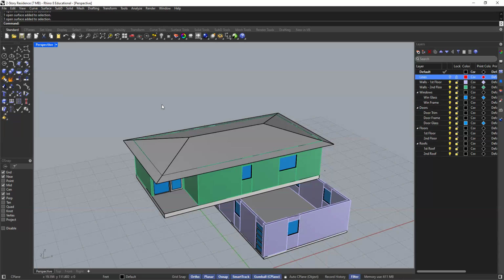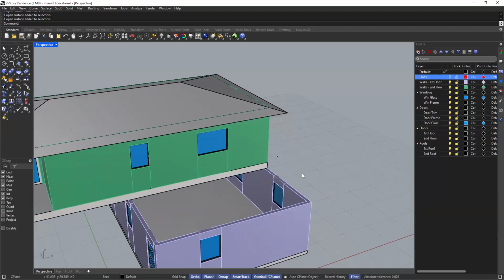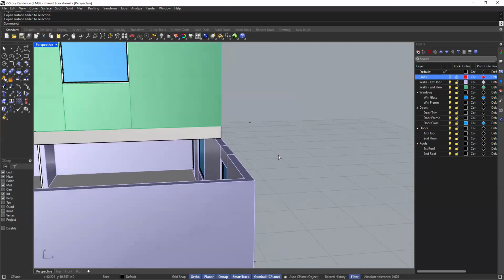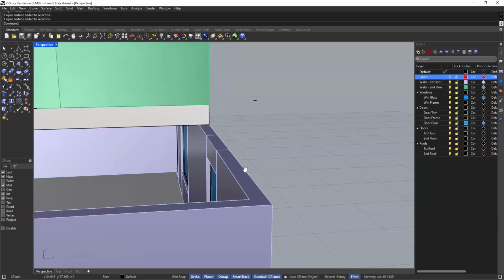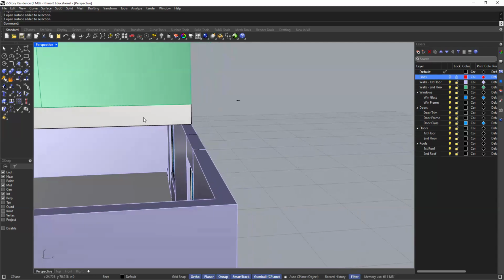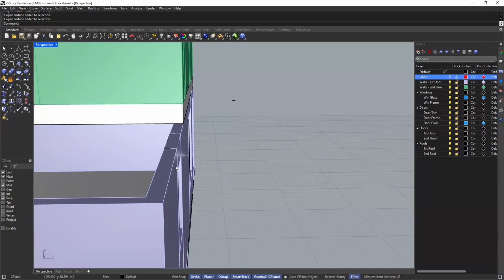Okay. Now here's the thing. Hip roofs, how do I explain? Hip roofs are actually constructed so that they sit on top of the wall, right? In other words, a rafter will come in at an angle. They kind of notch the wood rafter so that it just sits on top of the wall, and then they bring it down, and then they continue the angle, right?